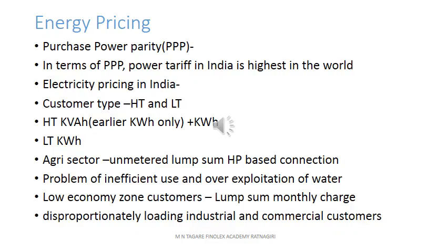The same thing is applicable for energy also. That same triangle is valid for energy, only all three sides should be multiplied by hours. So the power triangle is converted into an energy triangle. So here you will find, if I consider kVAh billing, obviously it will include the active energy, and at the same time it will also include the power factor.